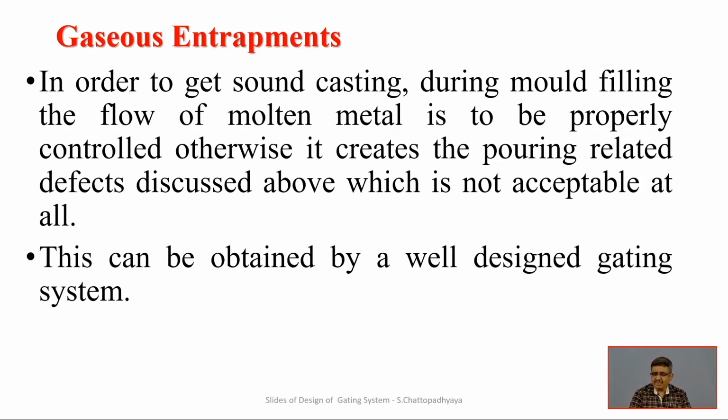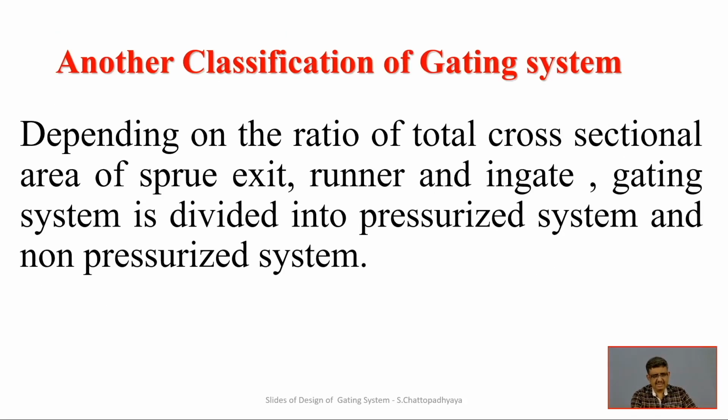We can discuss vacuum casting, where the possibilities of air entrapment and other things are less, because all those things will be done under vacuum with suction. That is why people are going for vacuum casting, so that this kind of entrapment of gases and other things is a little bit less.